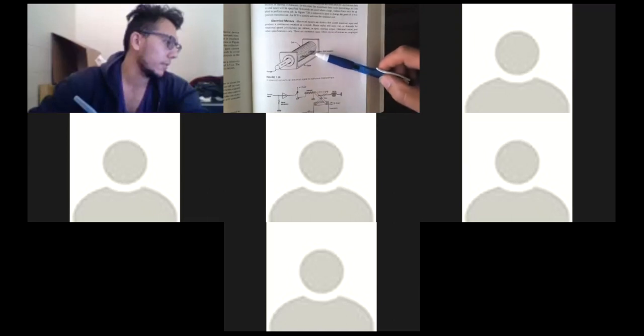Of course, you can reverse the direction of current, and then you have a two-directional plunger. You can push forward and backward, both directions. So this coil can have positive current. You can reverse the current, and when you reverse current, the plunger will reverse direction.